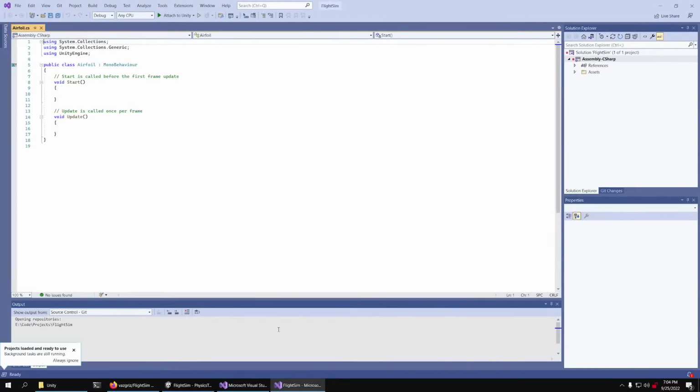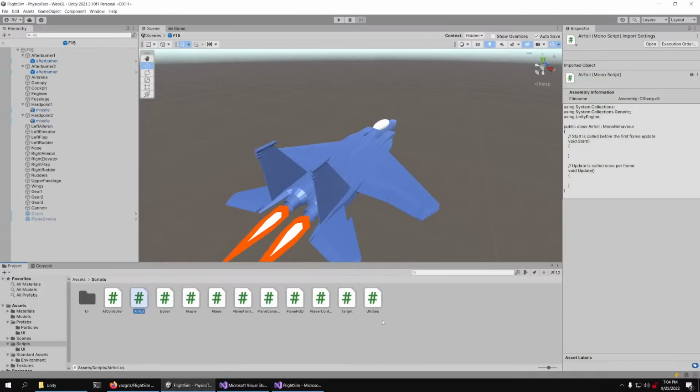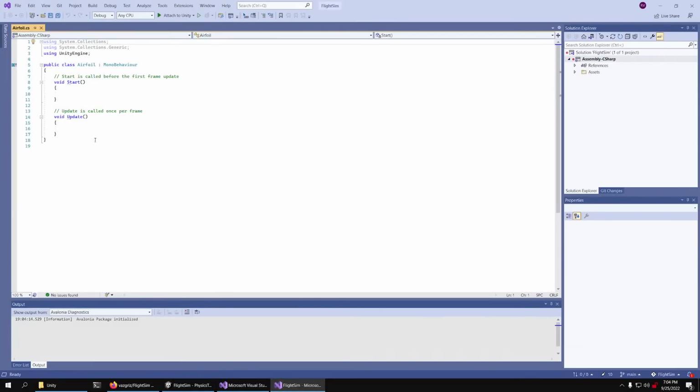Yeah, so one of the examples of how this could be more advanced is that you could in fact stall one wing while maintaining lift on the other one, which will cause you to roll uncontrollably. If you yaw left or right, that will cause one wing to advance and have a different angle of attack, and it will cause that wing to generate a lot more lift. So these are things that are not possible in the current flight model, but they should be possible once we have the more advanced flight model.